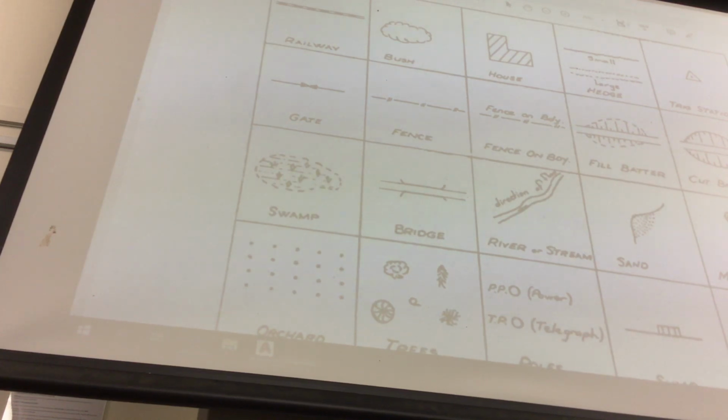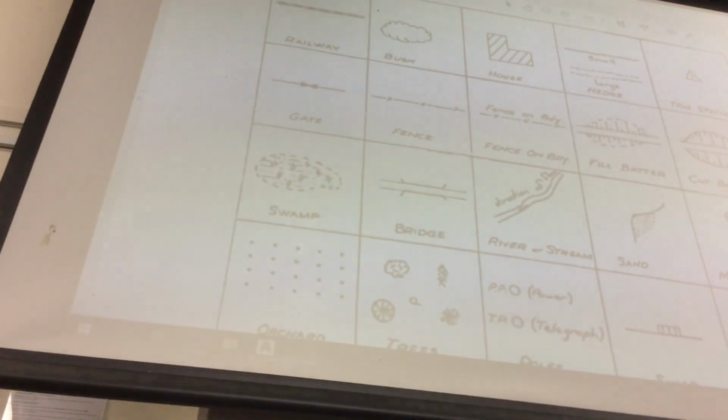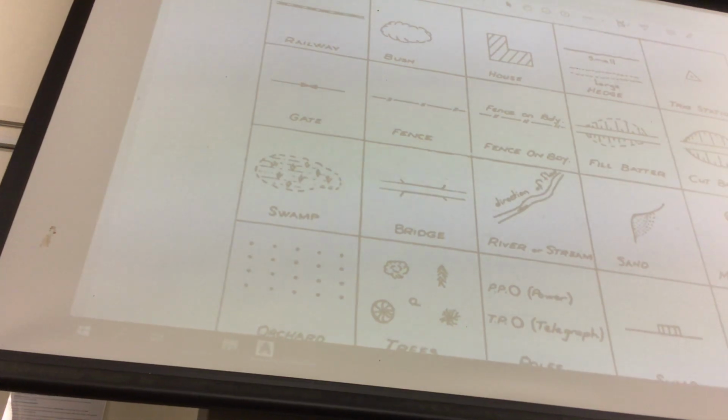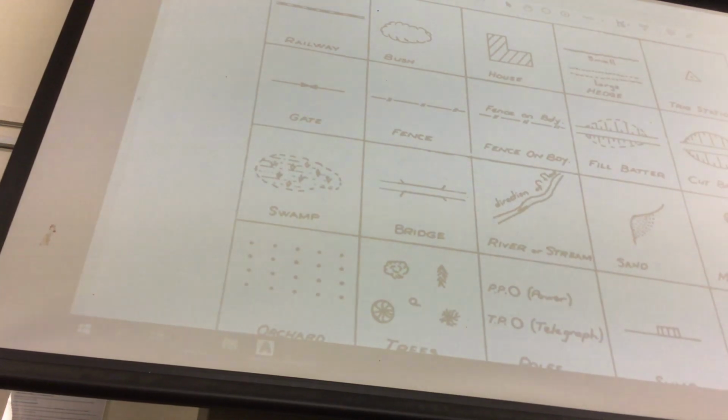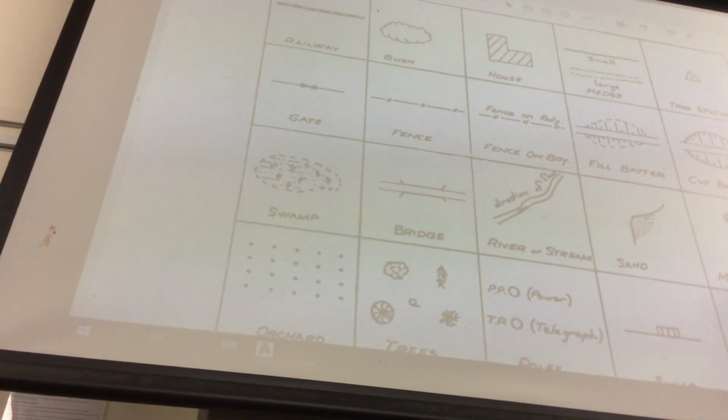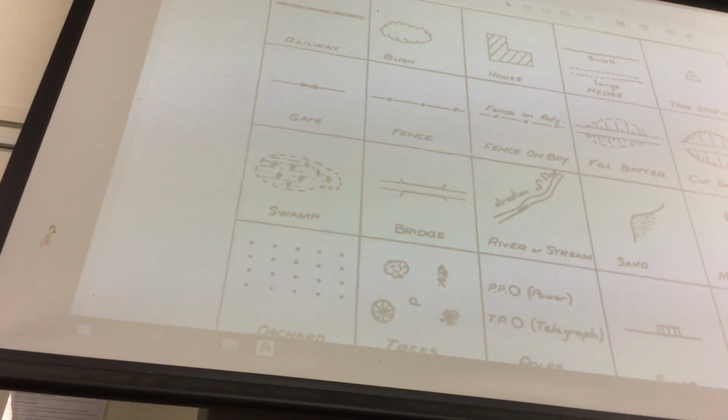So that gives you a bit of an idea of the manhole. No, I haven't done that in the assignment. Yes, I have done it here. Well done for attending class. I've talked about the tree this morning. That becomes an important issue as to where that is, but you're not quite sure about the earthworks just yet, but it may be something you're going to need to write on the plan. The manhole is a proposed manhole, so it should be with the lid filled in, because that's my company standard.